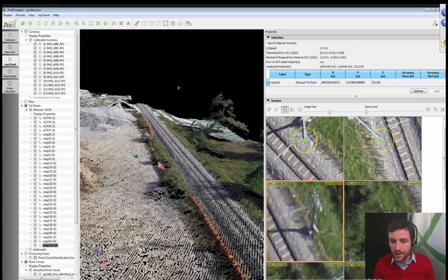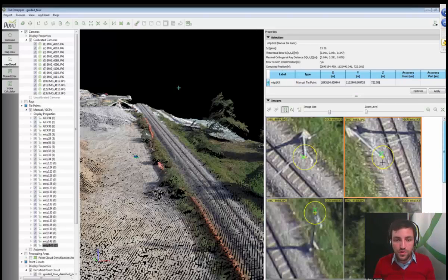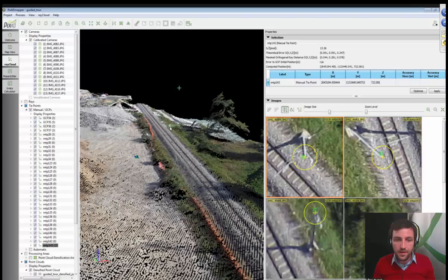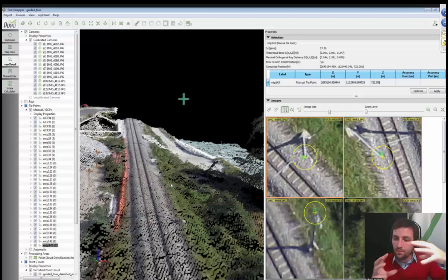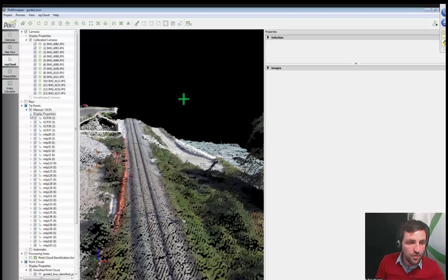So, for instance, here I can see that the point was not exactly set at the right place, and by refining and clicking more, I can adjust it. One very useful option to check visually how clicking more really improves the calibration, the definition of these points, is to go in Type Point on the left panel, Display Properties, and then to click on Show Error Ellipsoid.